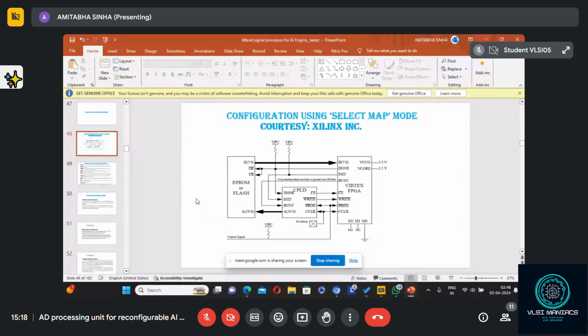Now, once you download the bit streams, they will have some specific area. So for each module, let's say for the FIR module, n number of bytes are to be stored. If it starts from location 0, then from location 0 to location n-1, the bit stream for FIR will be stored.